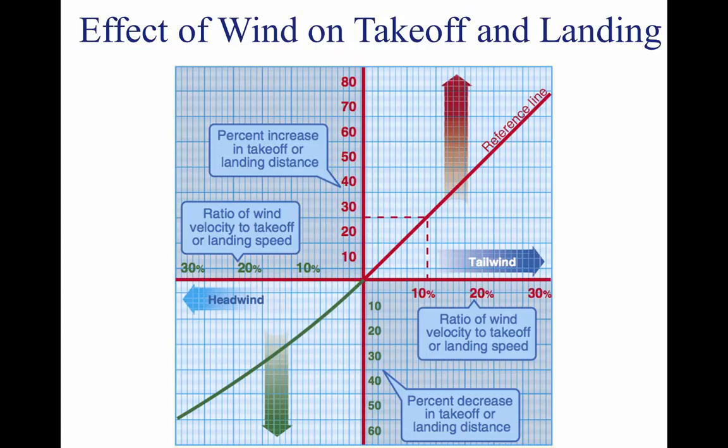A distinction should be made between the procedures for minimum landing distance and an ordinary landing roll with considerable excess runway available. Minimum landing distance will be obtained by creating a continuous peak deceleration of the aircraft. That is, extensive use of the brakes for maximum deceleration. On the other hand, an ordinary landing roll with considerable excess runway may allow extensive use of aerodynamic drag to minimize wear and tear on the tires and brakes.